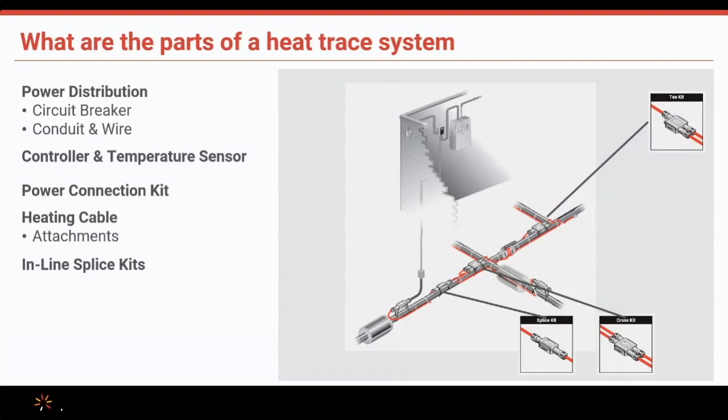In some cases, T connections aren't the right option. I will say that if you're looking at a diagram that shows a long pipe, and then you might have a short 5-foot T segment, and this is just a freeze protection application, instead of putting an expensive T connection there, my design preference is really just to double the amount of heat trace cable that would go along that T and come back to your main and then continue on the pipe as you go.